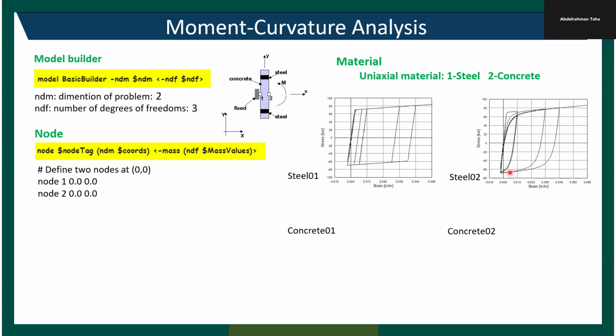And of course, this is facilitated by introducing more hyperparameters in the material model. And then Concrete01, basically in this model, we just have the compressive part or strength, and it's assumed that the concrete doesn't carry any tensile stress, and that's why the tensile part of the material model is fixed to 0, so no tensile strength here.